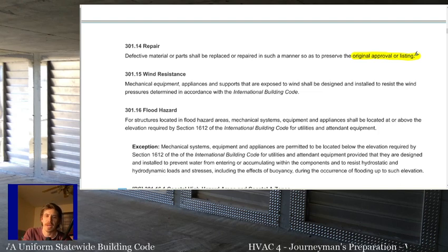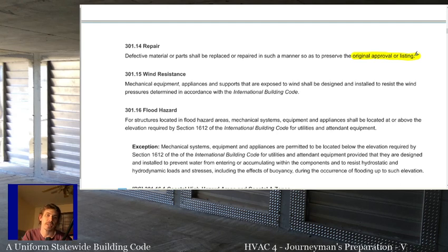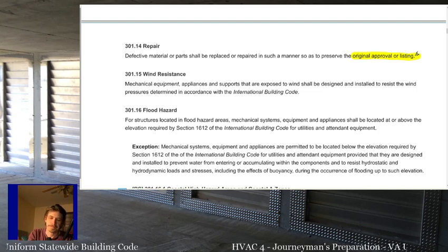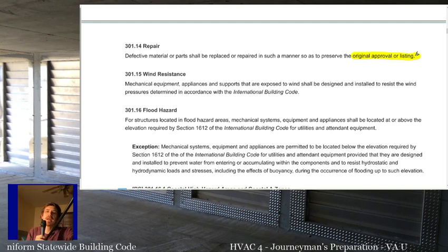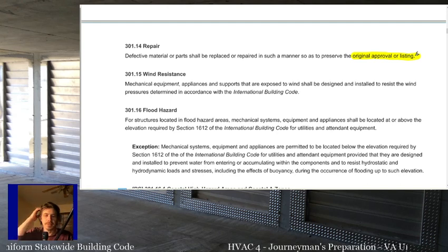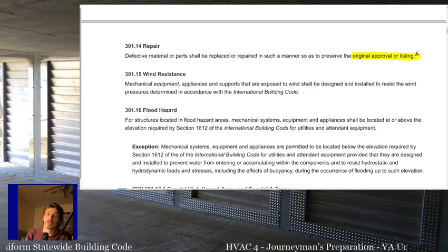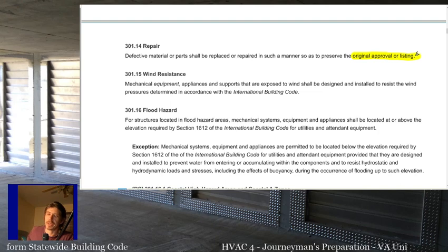So that's why you get factory reps sometimes that'll come out and say they can't make a certain change to the equipment because it would then no longer be listed, or it changes how the equipment functions. I've had that happen before, on a Trane RTU that had a reversing contactor. We could have removed it, didn't really need it anymore, but technically that would change how it's listed, so you can't just delete that component.